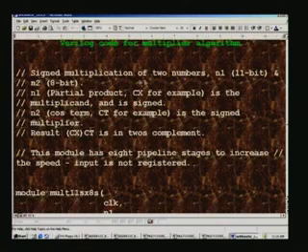So we have two numbers, n1 and n2. n1 is 11 bits and n2 is 8 bits, and both of them are signed numbers. Internally, we are going to temporarily remove the sign, apply the algorithm only on the magnitudes, and having got the final result, we will sandwich the sign bit back at the very end. So here n1 and n2 are 11 bits and 8 bits, and the 11th and 8th bits will be the sign bits.